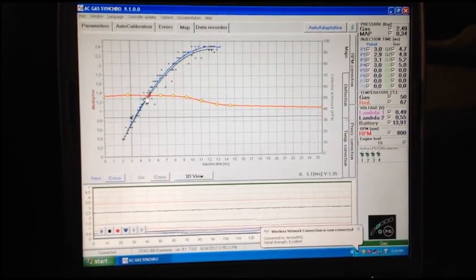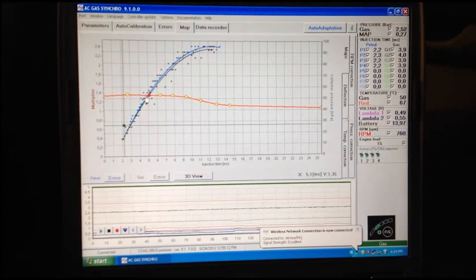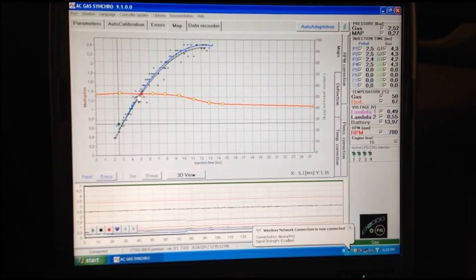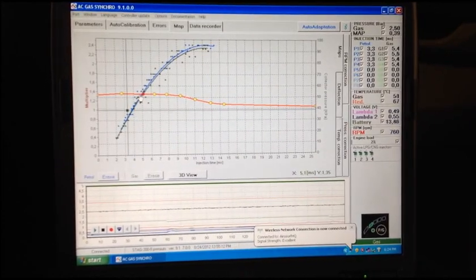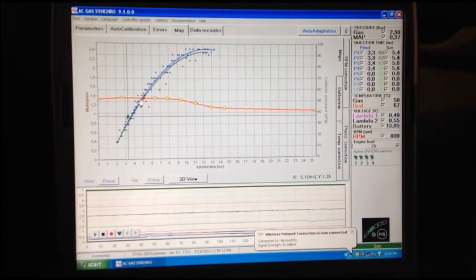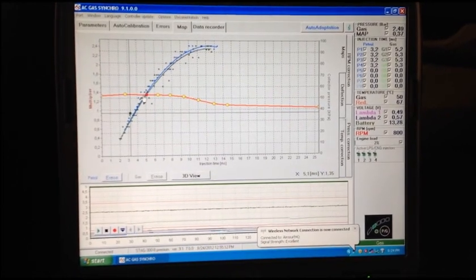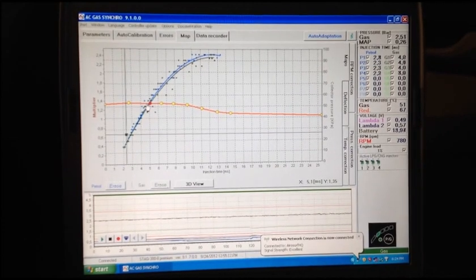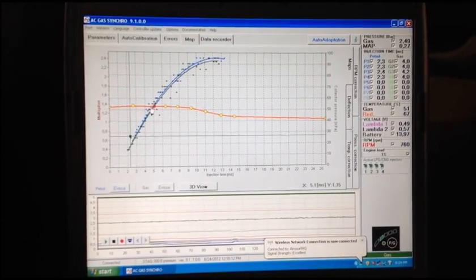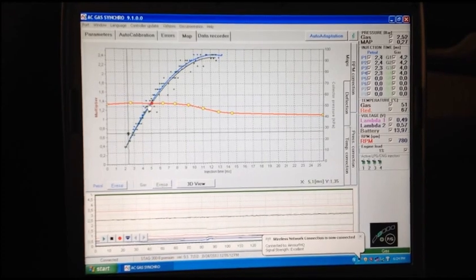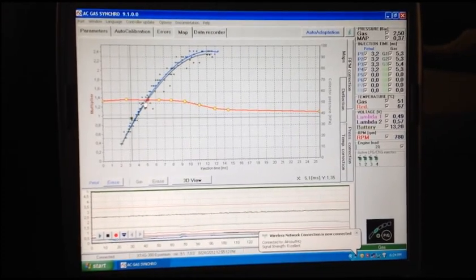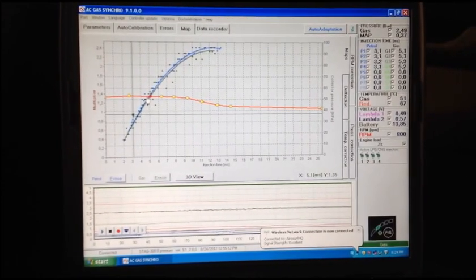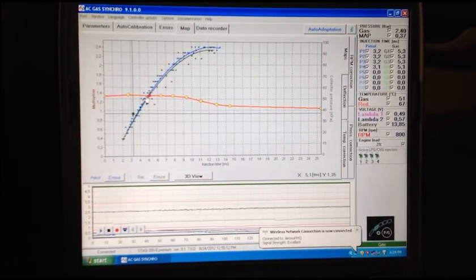But in some vehicles that do still have an open loop mode, and older vehicles will go into open loop at even a much lower load, that's the opportunity that you have essentially to lie to the system and run it just a little leaner, because natural gas has a 17-to-1 ideal ratio, where gasoline is more down around 14-to-1. So you can dial in a little extra power up there in the load areas where it's in open loop,